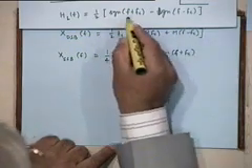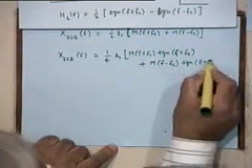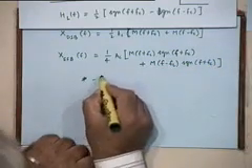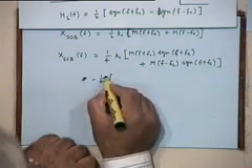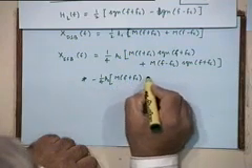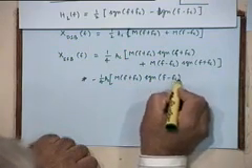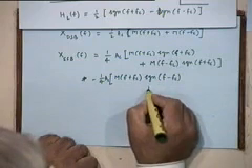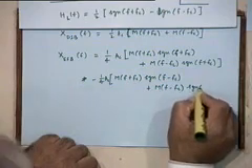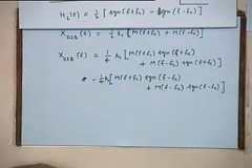So I am taking these 2 terms and multiplying with this: signum(f + fc), plus minus 1 by 4 Ac M(f + fc) into signum(f - fc). Please check that I am doing things right, plus M(f - fc) into signum(f - fc), right? These are the 4 terms you will get.